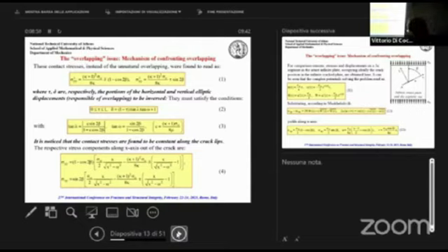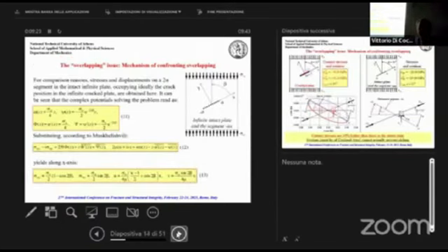We invert portions of the elliptic terms of the displacement field, and what these portions are depend on the specific geometrical conditions of the problem. So the factors P and delta, the portions of the elliptic displacements that are to be inversed, should be checked and discussed in each case independently.